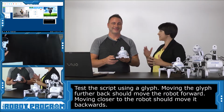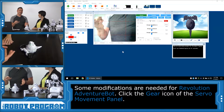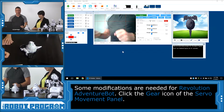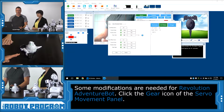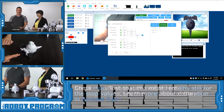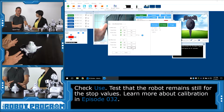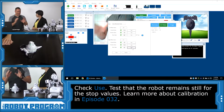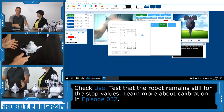So now we're going to execute the same code, but with AdventureBot. So there's 3 changes that need to be made to AdventureBot for our program. Okay. The first is inside of the servo movement panel. You're going to click on the gear, and you want to check the use checkbox, and then push the test button on each of the stop values, and your robot shouldn't move. Okay, and that's good when it doesn't move. If it does move, check the calibration tutorial and calibrate the servos.